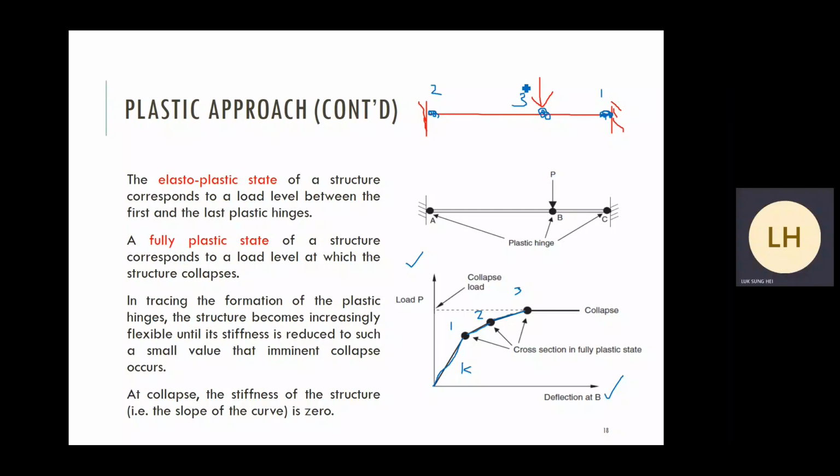At the location where the third plastic hinge forms, you see this three hinge arrangement. Normally, a beam with these three hinges will become unstable because when you increase the loading slightly, the member can deform in the downward direction without any big restrictions. After formation of three plastic hinges, it seems that the member starts to become unstable. We can also take a look at our force displacement diagram.